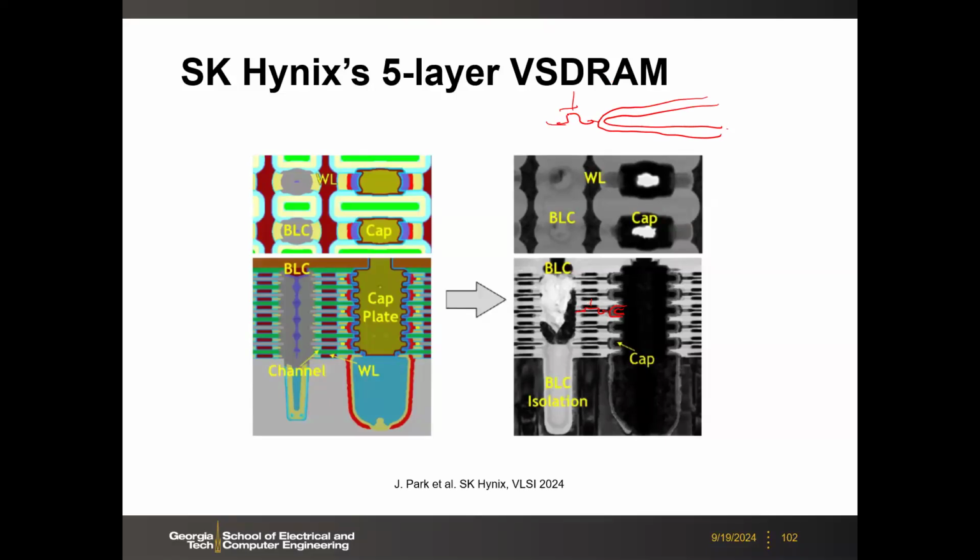I met the SK Hynix researcher a few weeks ago, and I asked him why this C is so short. He said in the initial design they underestimated the cap, and the retention time was not so good in this initial design. So they admit that the C should be larger. They said this was not the finalized design.